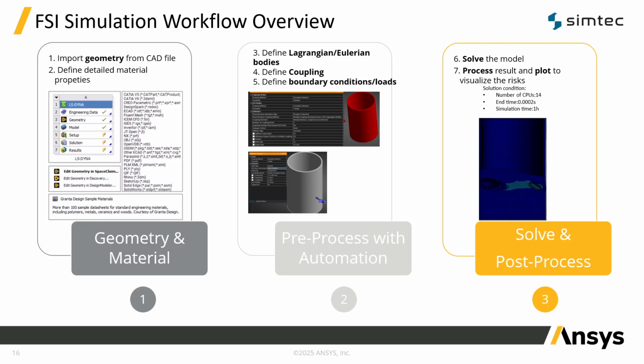For this example workflow, the solution is conditioned by my number of CPUs and by the end time that I inputted in analysis settings. As you can see, I used 14 cores and 0.0002 seconds end time. And with those parameters, the simulation time took 1 hour.